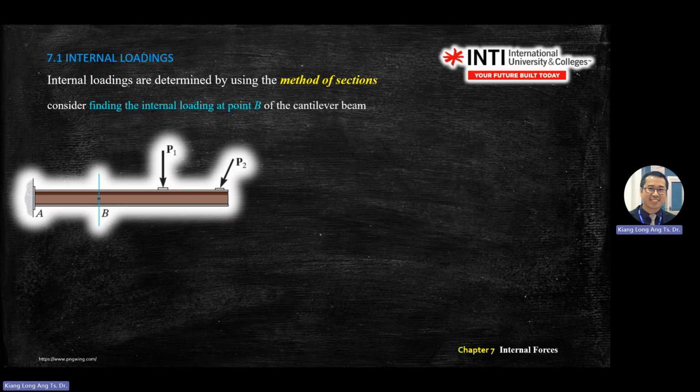Here, how we solve all these things? We use equation of equilibrium. All the force equals 0. All the moment equals 0. It depends on which one, how many unknown you have. So that's why this one, all the force equals 0. You can split into x direction, y direction, z direction. Moment, you only can catch any point you want. It can be A point, it can be P1 point, it can be P2 point. Okay, so this depends on how many unknown you have.